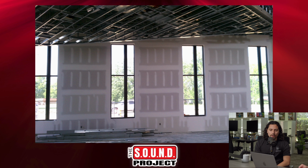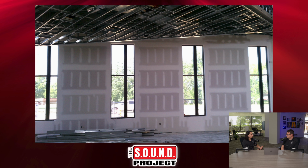Yeah, and that's somewhere where a client that wants a livelier environment has the splaying of the walls, where they're not having a lot of parallel wall space in this room. If reverb time doesn't need to be too low, you might not need as much treatment, but reflection buildups and harsh reflections will still be an issue even if you have a higher reverb time. Angling walls a bit, by at least 10 degrees, can be a really good way of mitigating those issues. Sure. Yeah, it's a great way to do that and keep the reverb time intact.